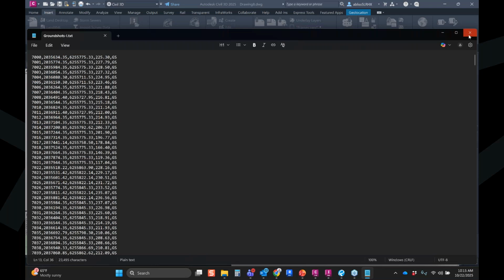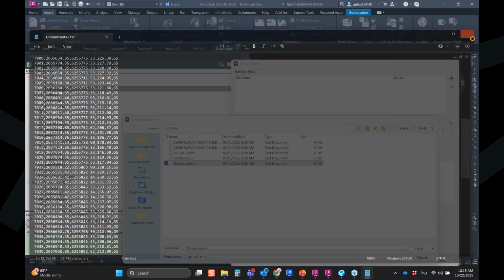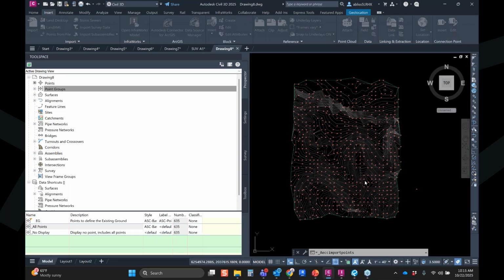And so just that simple point file of all your points, and then you quickly got a surface, and then you're saving your drafters, designers on your team all that time, building out the surface, building out the point groups, all of that. You fully automated and standardized that process. So it's a good best practice to add into your tool belt.